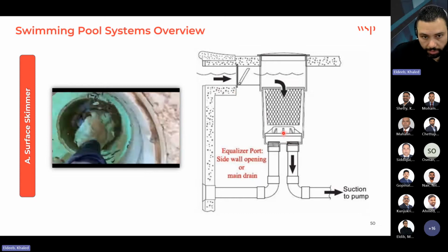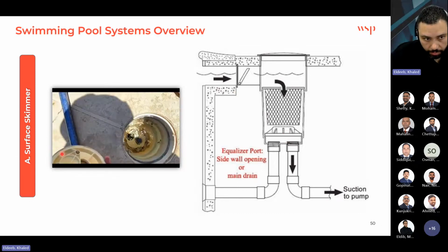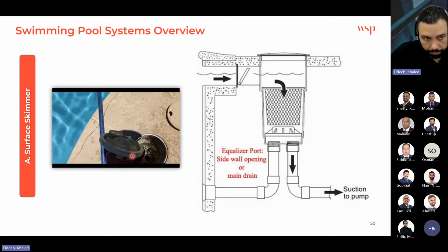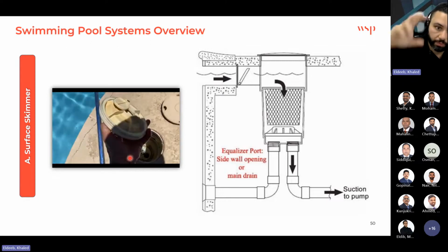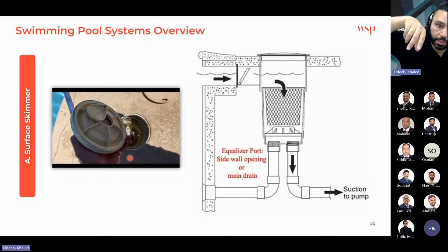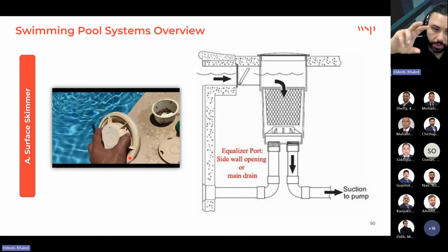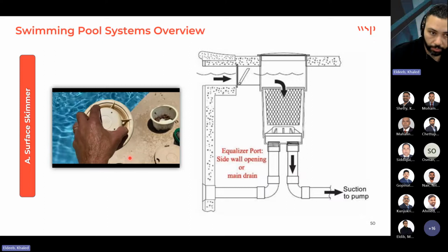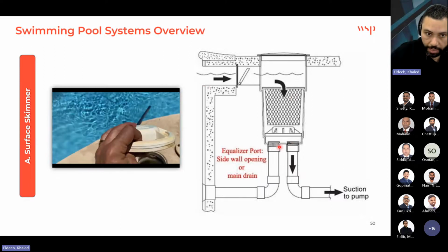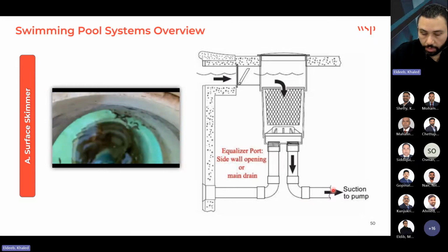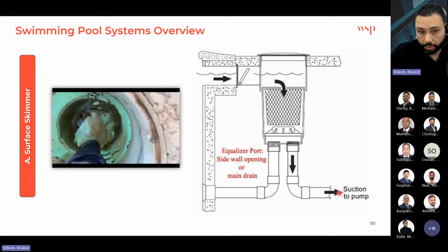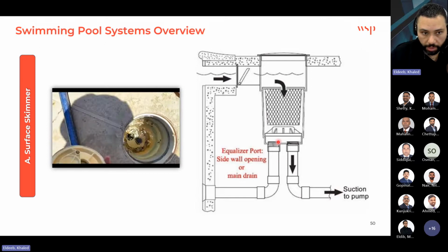Inside this diverter plate, they have a plastic bowl floating with the water. If we have enough water, it will go up and allow the water to get in, and if the water level goes down, it will automatically go down and close this side and open this side. So the water will go here and always keep the pump suction wet, not dry, to protect the pump.